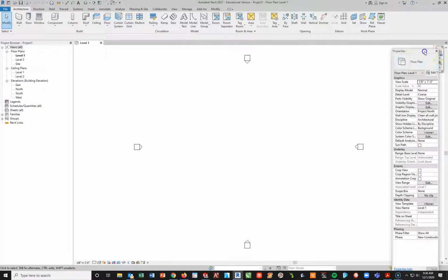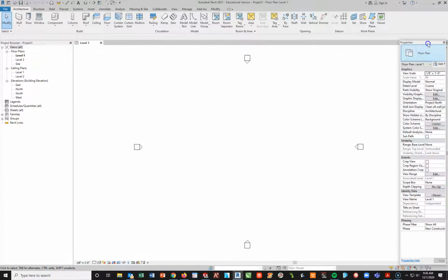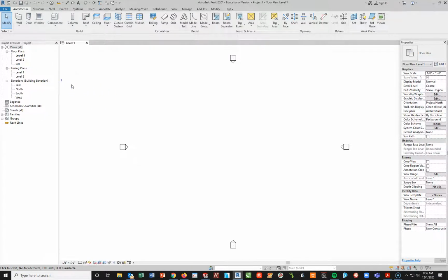The reason I want to keep this is just it helps to have these two separated. It gives me more detail. Whenever we click on something in our Revit, you're going to see this properties tab here will basically give you all the information about this design. Okay, so if you're clicking on a wall, it will tell you the size of the wall, what type of wall. You can do a bunch of different things to the properties over here by editing from this side. Okay, so it just makes it easier than trying to have it where in your screen it probably came up as a lower half over here, which isn't very big. Okay, you can also adjust these and close these down, giving you more drawing space. It's up to you how you use that.